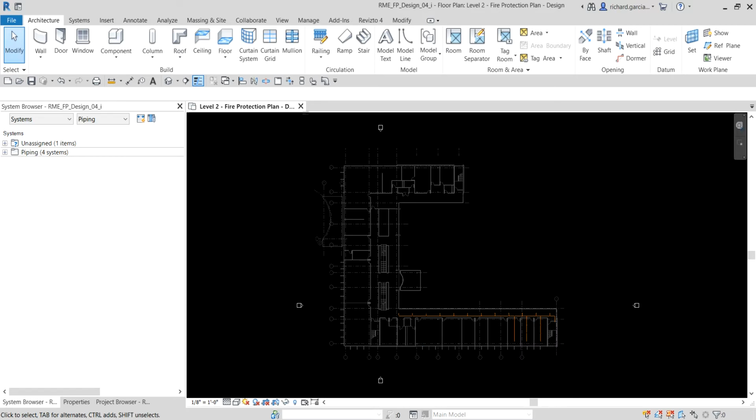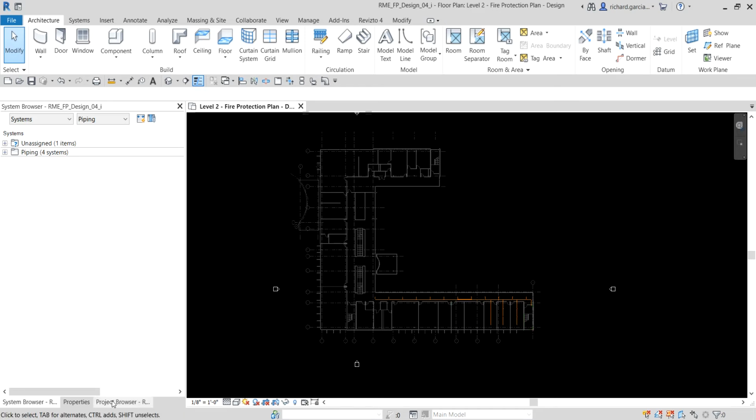After learning the fire protection wet system piping, this time around we're going to continue our modeling by adding vertical supply piping. So in this exercise, we're going to create a section view that I will use to work with the vertical piping. And then I will also place a hose reel cabinet in the building and connect it to the supply standpipe. Okay, so I'm going to check my project browser here.